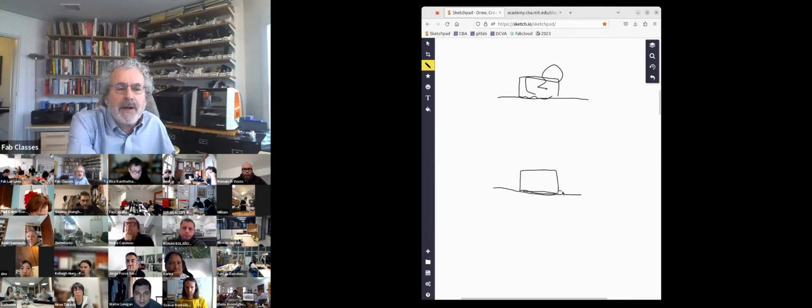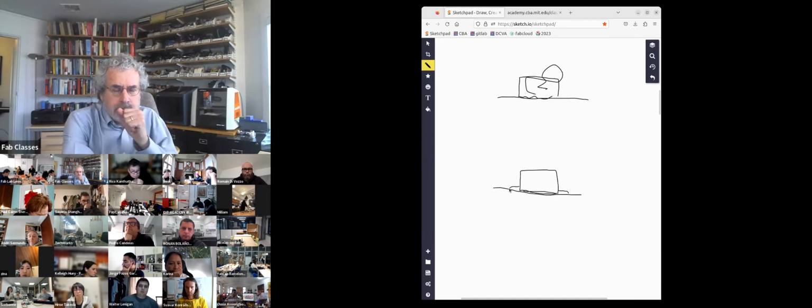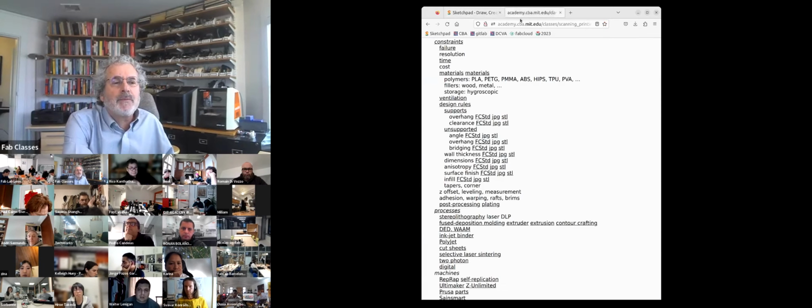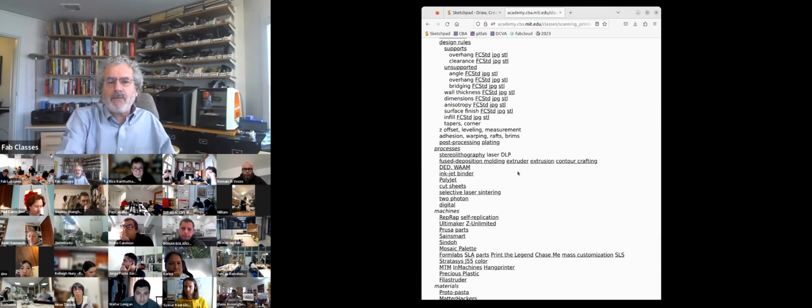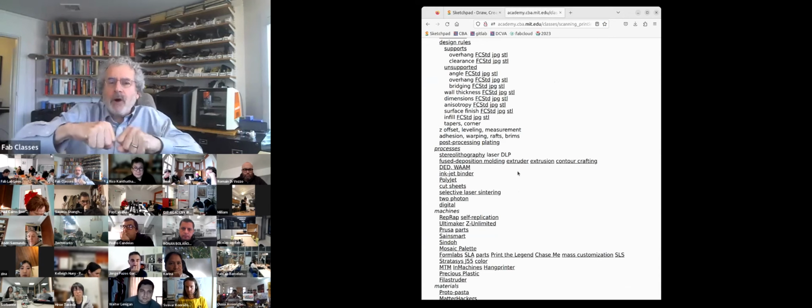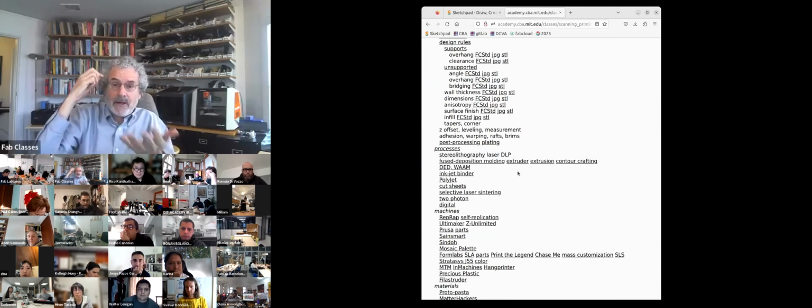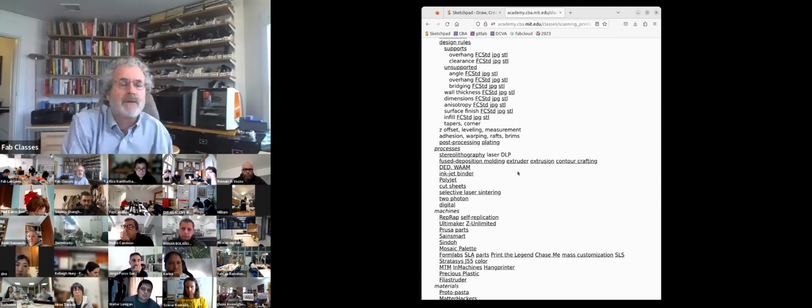And then you can print a brim, which is a lip that helps hold the part down. So you'll have to experiment with your printer and your process, but typically cleaning the bed and adding rafts and brims will help with parts that, as the part cools, can bow a little bit, and that's part of what causes it to come off the bed.